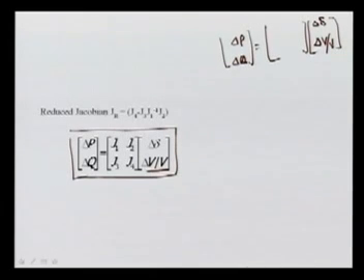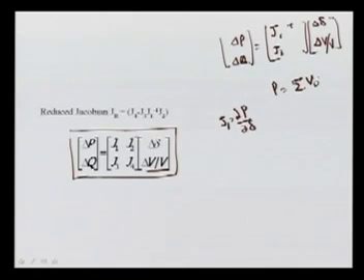But here in the Newton-Raphson load flow, we normally divide by V. The question arises, why? The main reason is this: if we go for the differentiation for J1 and J3, because you can write this P equation, J1 is nothing but del P upon del delta. Here you can see P is a double summation of V_i V_j, again a function of cosine and delta.